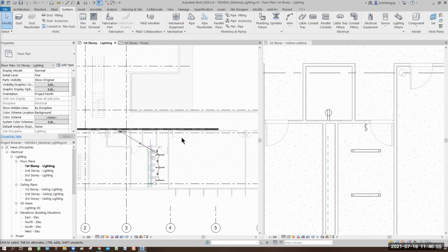If this room doesn't have a sub panel and we leave it at the FCC, it means every maintenance staff or trainer must call up the FCC and say, hey, this room got no power, then they have to turn it on. Troublesome, because it tripped. So I don't think they want it that way. They will normally branch out, minimizing maintenance and calling here and there. I think this should be the correct way, right?